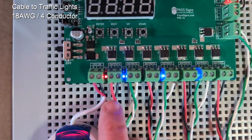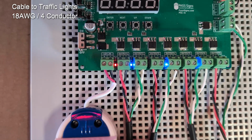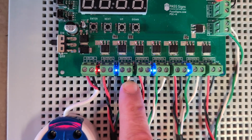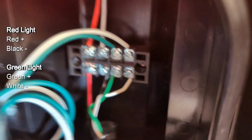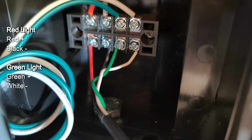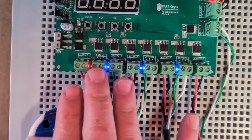As you can see here, I've wired up, I just use an 18 gauge 4 conductor to the traffic light. I use red and black for my reds, and green and white for my green light. And back here on the actual device, you can see right inside there, same thing. Red, black, green, white. Very simple, straightforward to manage.